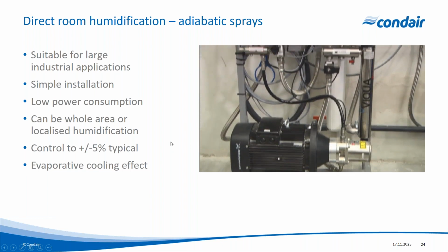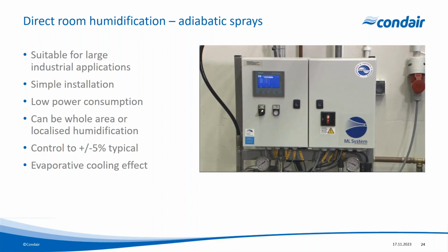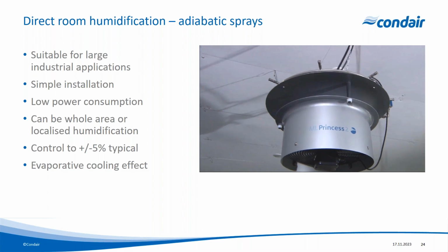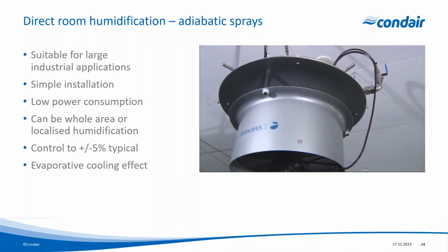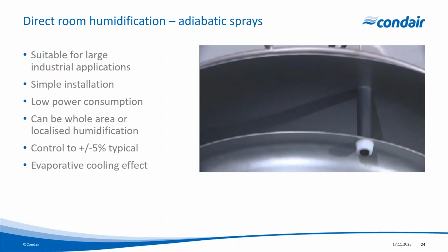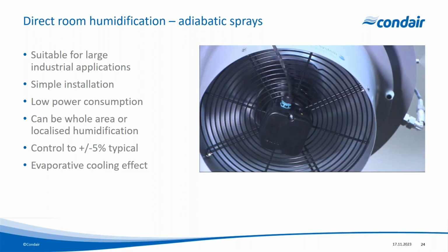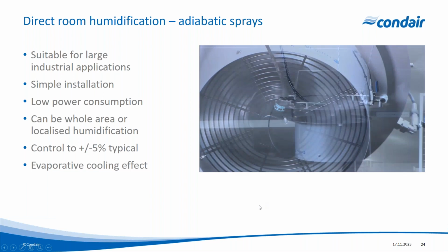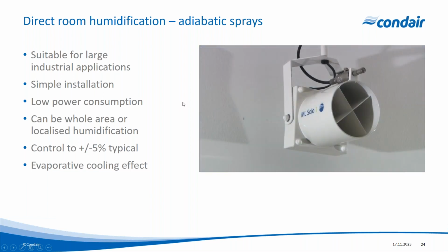So these are great for large industrial applications where you've got a large area and you want to holistically humidify the area to allow all of that area to conduct a static charge to Earth. And the systems typically consist of a series of spray heads. This one is a fan-assisted spray head, so air will be drawn up through the spray head and then assisting the aerosol to be distributed.